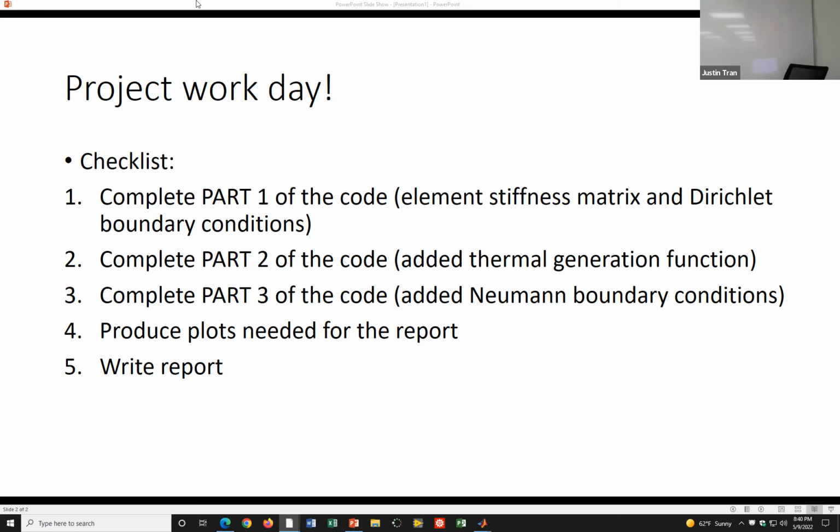I wish MATLAB would give an error for this, because it should be an error, but if it's defined earlier, it's just going to reuse those. Because you're not updating IND1, IND2, IND3, you're taking all your element stiffness matrices and putting them in the same place. So we're going to go ahead and put this here.